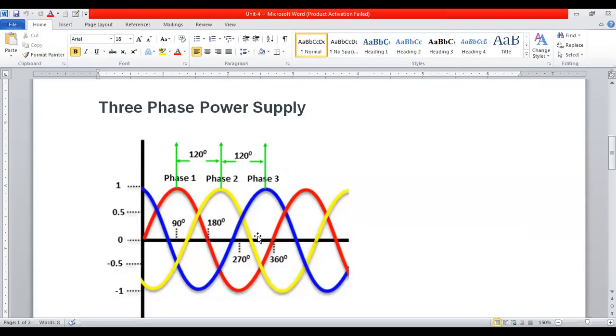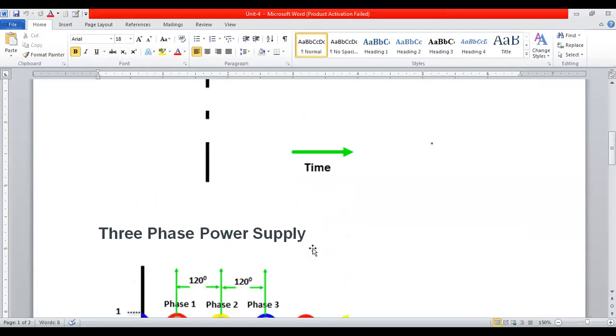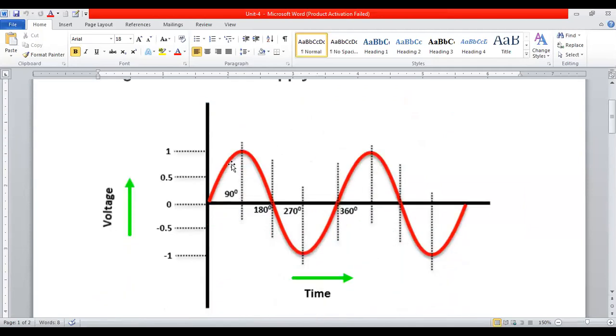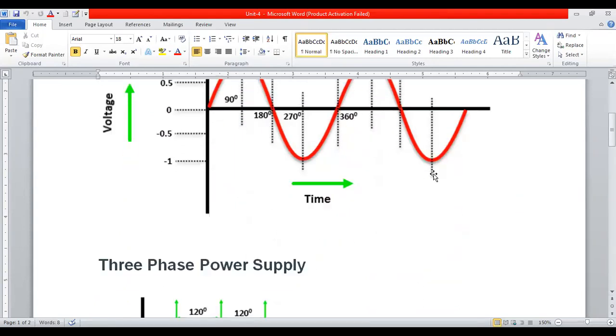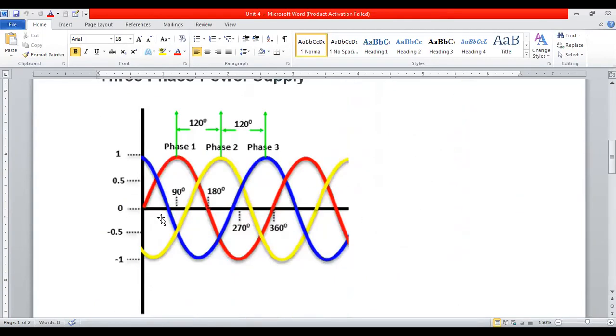Again, its graphical representation will be like this. See, this is the single phase AC voltage. Number of times we have seen V of t, Vm sin of omega t, or i of t, Im sin of omega t. Same nature, whatever the 3 phase AC supply. See, first equation Vm sin of omega t, Vr, which is the red color waveform. We know its first positive peak occurs at 90 degree, isn't it?